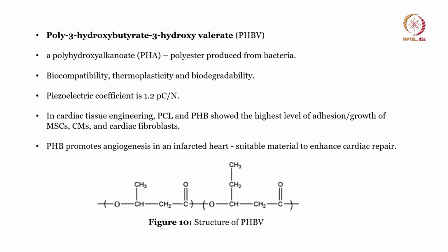So, next, another important piezoelectric polymer that is studied is poly 3-hydroxybutyrate 3-hydroxyvalerate, in short called PHBV. This PHBV belongs to a class of polyhydroxyalkanoates, where it will have an ester functional group. Here you can see, ester functional groups are present in the material. So, that is why it belongs to a class of polyalkanoate, and this polyalkanoate is nothing but a polyester material synthesized from bacteria under excessive carbon and nitrogen atmosphere.